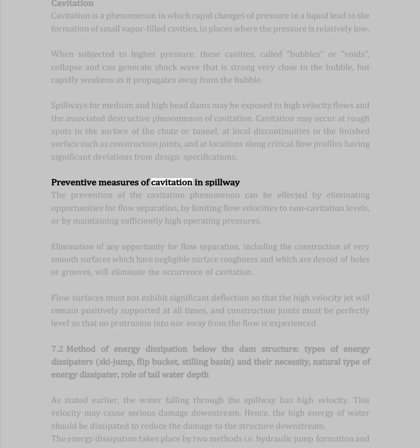Preventive measures of cavitation in spillway. The prevention of the cavitation phenomenon can be effected by eliminating opportunities for flow separation, by limiting flow velocities to non-cavitation levels, or by maintaining sufficiently high operating pressures.